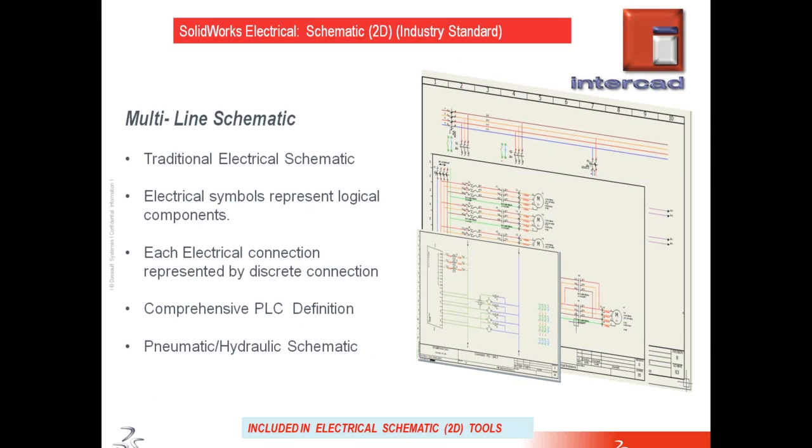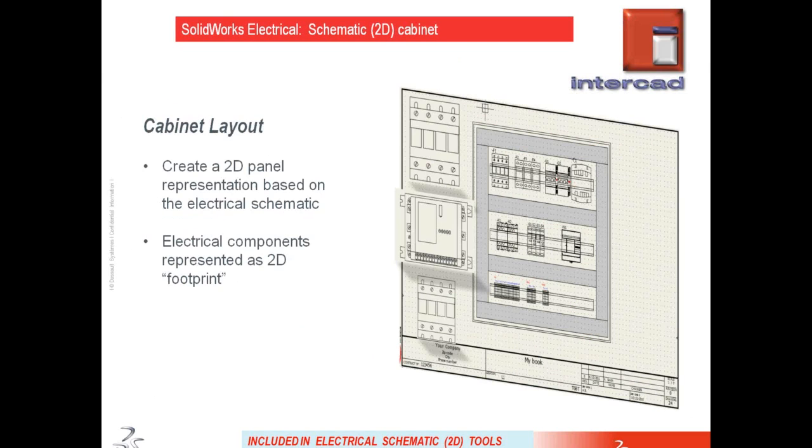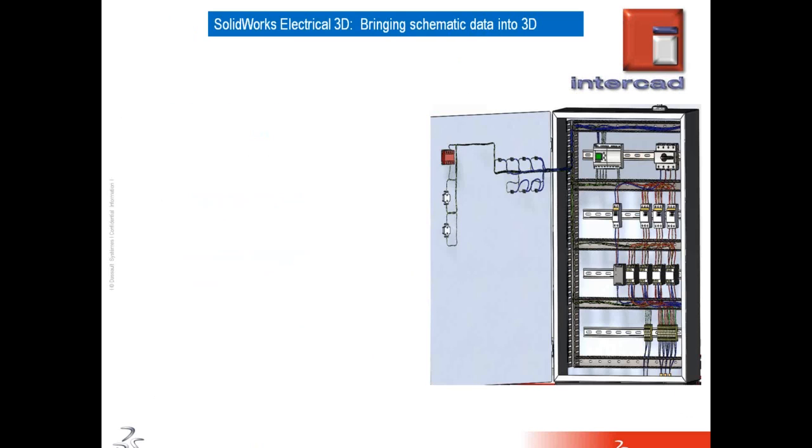And as you've also seen, you can do hydraulics and pneumatic schematics in that. And the benefit of doing everything in one package is the cross-referencing between all the drawings, so you're not hunting between one drawing and another and manually finding the product. You can simply right click and use the go-to commands to go to the different drawings within one project.